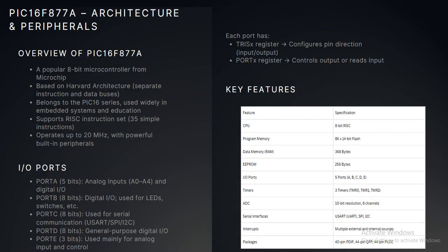It has 5 input or output ports, 3 timers, 10-bit ADC, and then EEPROM, and communication interfaces like UART, I2C, and SPI. You can see the clear-cut explanation about these communication interfaces. And then we can see the key features of this PIC16F877A. Moving ahead,